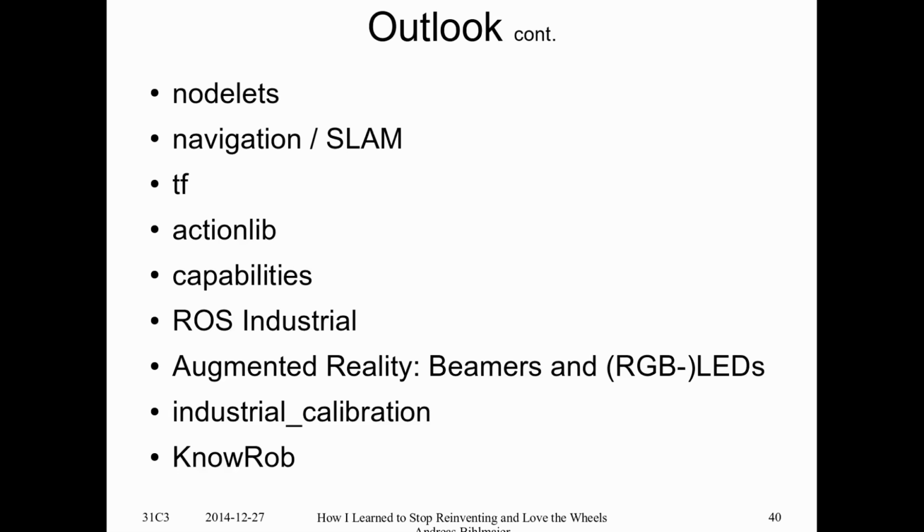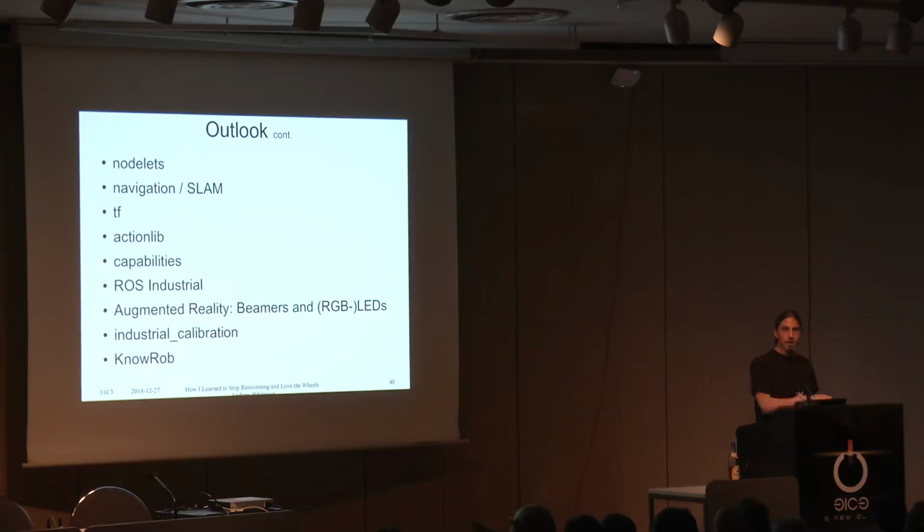This was a really huge scientific research question for the last 10 years. And now we have open source software that does this reliably for indoor scenarios. So basically you have your Roomba, stick a Kinect to it, configure the navigation stack, and you have SLAM, which many, many PhD students worked hard on for the last decade.